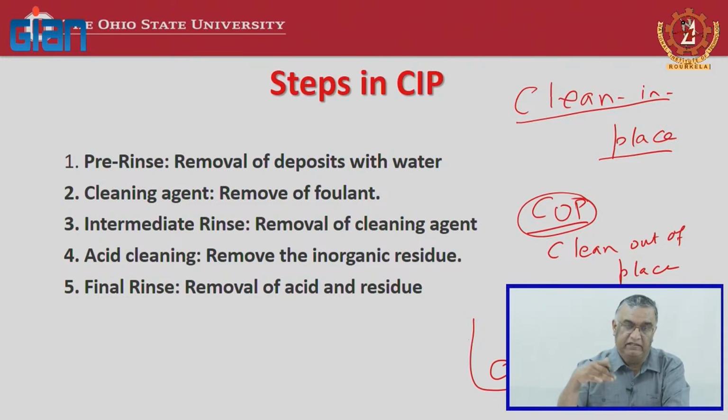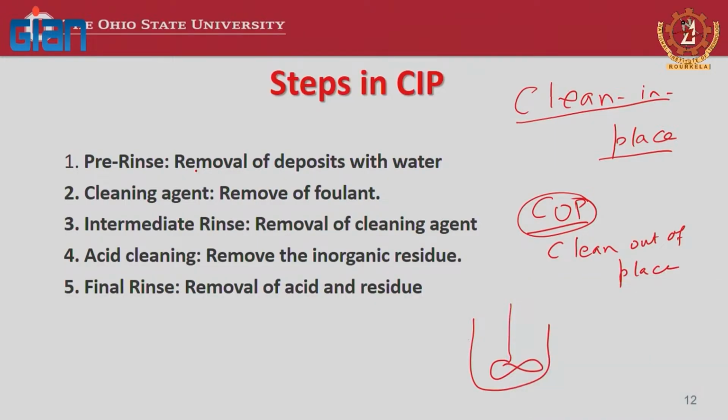So, the idea here is you do it without disassembling, by maybe passing a pre-rinse step. There is a sequence of steps. First, you take that pasteurization or aseptic processing equipment, and you just rinse with water, so that any deposits are removed. If you are processing some soup, you may have residue soup left on the equipment surfaces, so you clean them by rinsing with water.